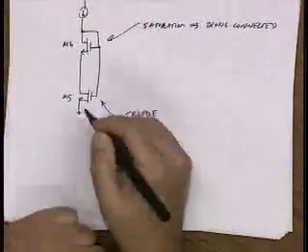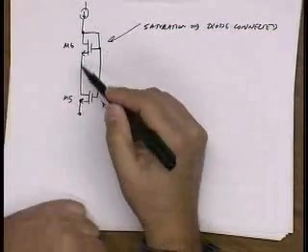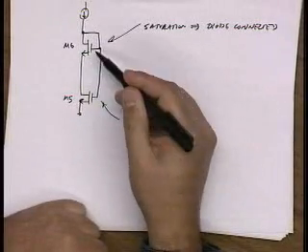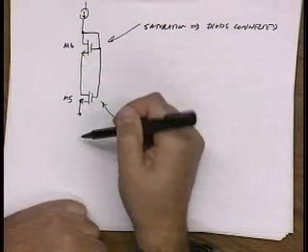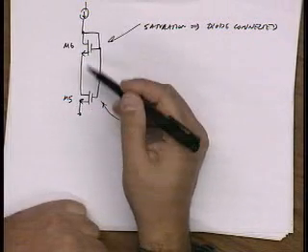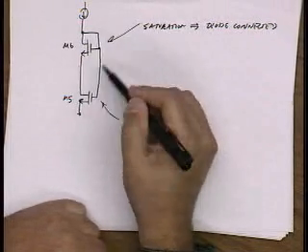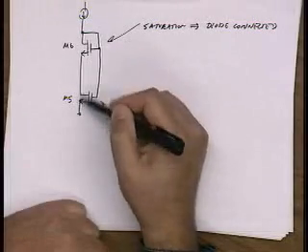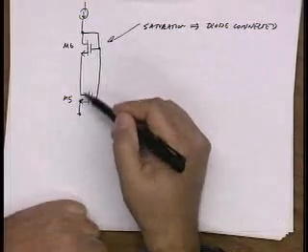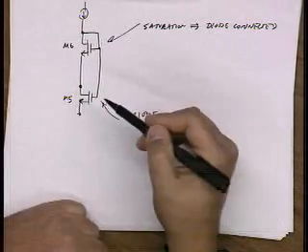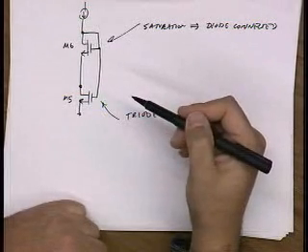That's good intuition. So the intuition is that this looks like one transistor, right? I've just taken one transistor and broken it up into 2. And so if the top part is the part in saturation, the rest has to be in, there's got to be a channel at this point. And if there's a channel at that point, that means this device is in triode region.